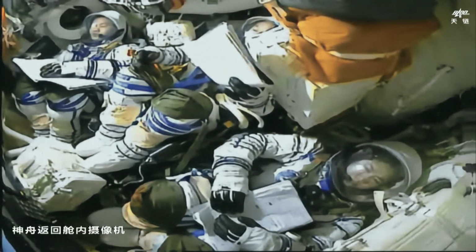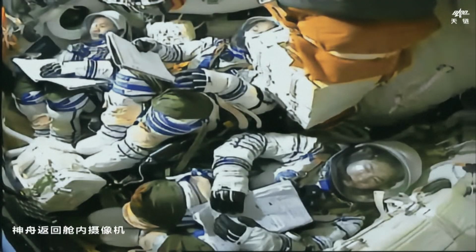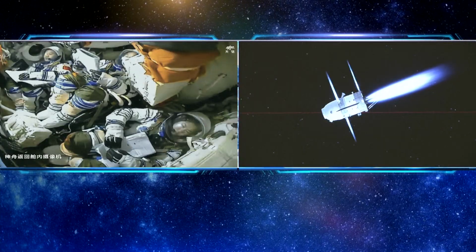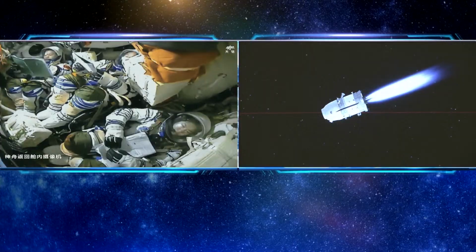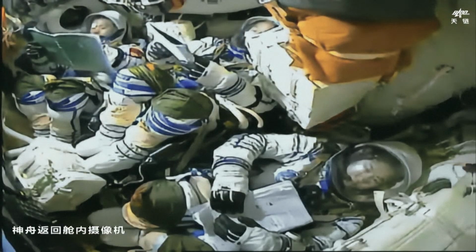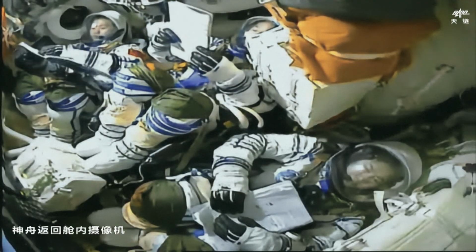Yes, exactly. From the previous video we can see that although, as you mentioned, it is a 3D animation, it represents the real-time status of the spaceship. At this moment, we are conducting the deorbit burn, which means we decelerate, shedding a remarkable amount of energy, so that the trajectory of the Shenzhou spaceship changes from a circum-Earth orbit to a trajectory which can dive into the atmosphere. With this very important measure, we can return to the Earth with the help of aerodynamic forces, which reduce the speed of the spaceship, and then we can deploy the parachute and come back to the Earth.